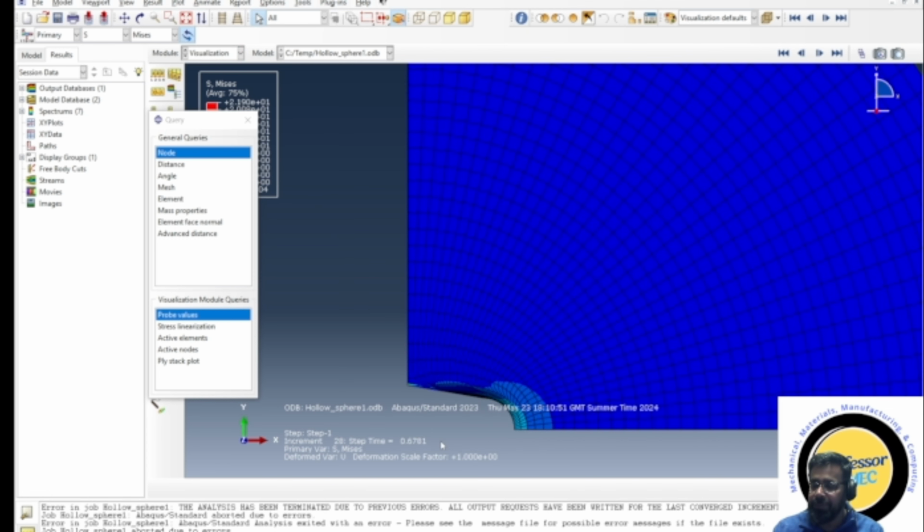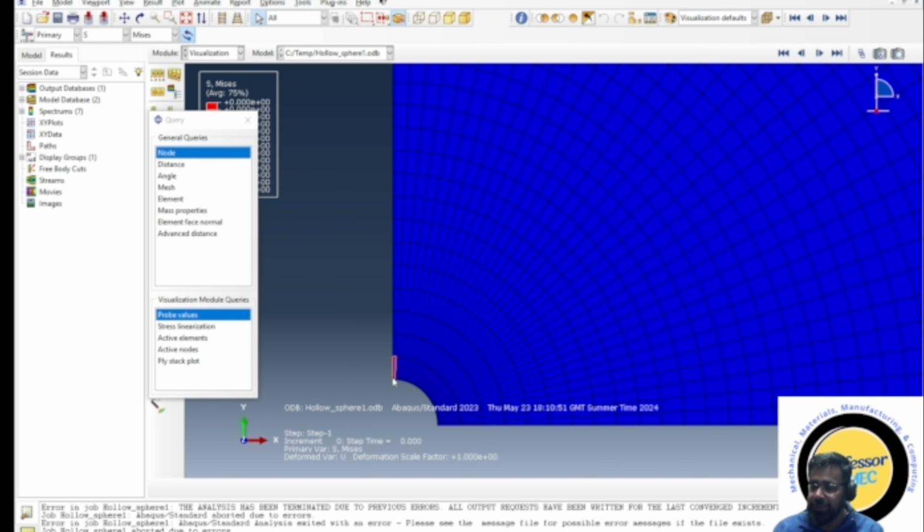These constraints you have to check because currently you are applying constraint on this point as y-symmetric, x-symmetric, and also you are constraining it with the reference point. So this common node has 2 constraints, and ABAQUS applies the last one, which is the boundary condition one. So hence the other one is removed, and that's why it just keeps on moving around. I think that's what is happening. So MPC is still active. So have a look and see what it wants. If I were you, I would try to model it as 1/4 or 1/8 of a sphere, and then it will be easier to deal with all these problems.